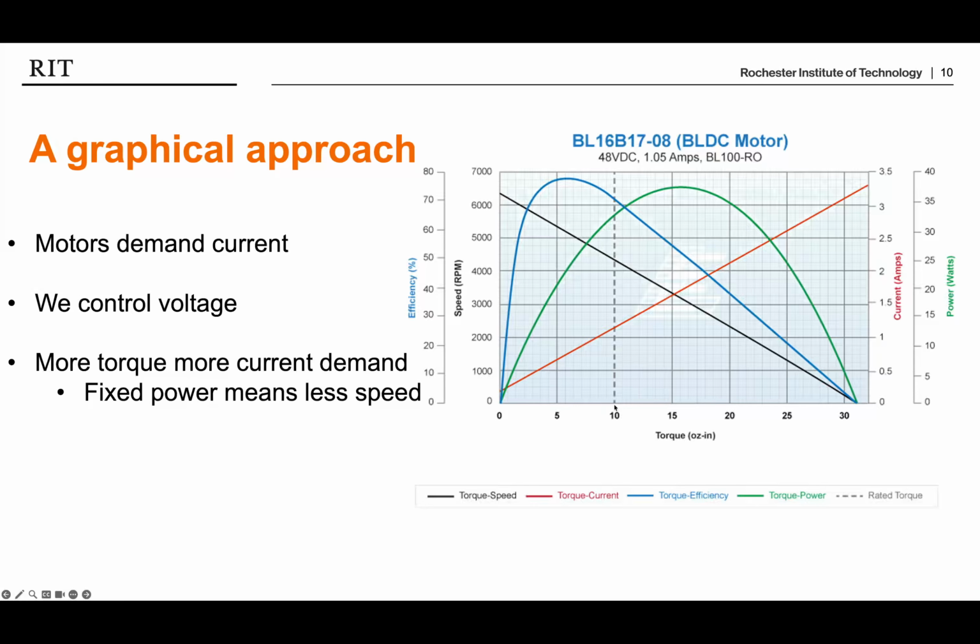And if I pick any point along here, maybe a 10 here, for example, I'll take this 10 ounce inches, come up, find my speed, multiply those two numbers, and plot them. So as I'm moving down this line towards the center, sure, my speed is getting lower, but my torque is getting higher. And since there's a slope of this line, this is going to generate, oh, look at this.